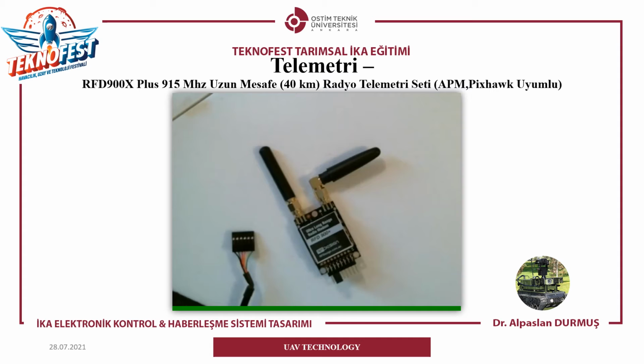Good habit, good practice. I suggest putting an antenna on any output on any transmitter. Because when it transmits and it's expecting a certain amount of impedance, if there's no antenna there and there's no impedance there, you can send too much power through the finals of the radio and you can damage the radio. So before powering the radio, always make sure you have an antenna connected to the output.